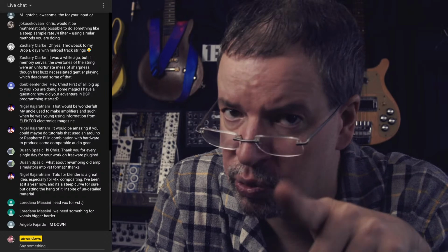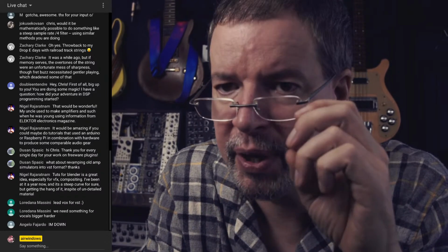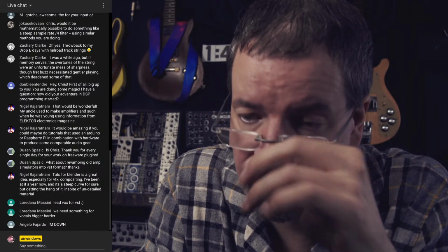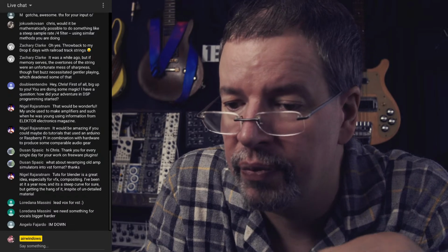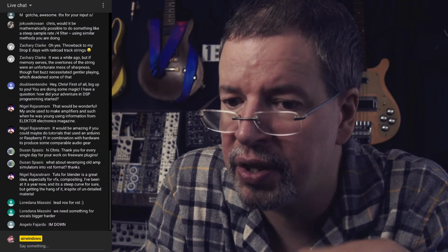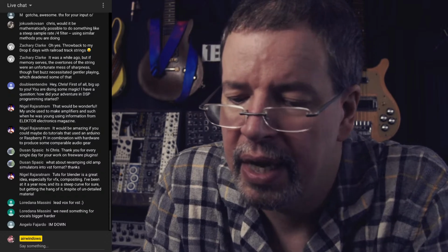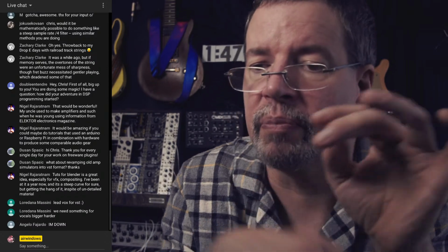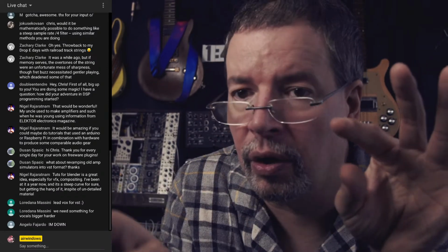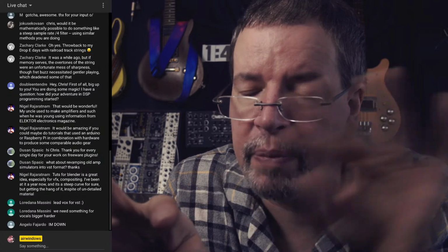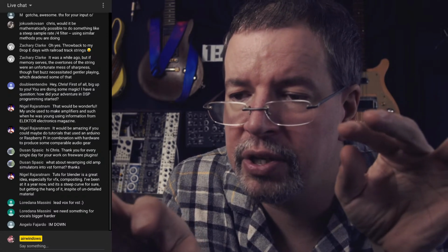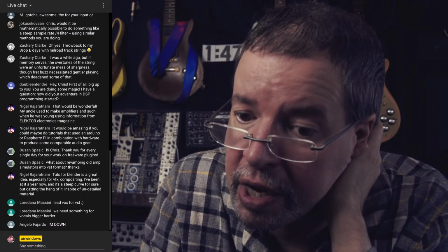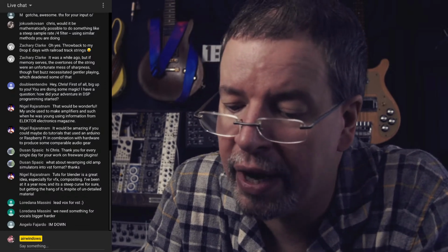You can do stuff like this in VCV Rack as well. It keeps stepping through. So you have your trigger value or whatever, your high logic value, going through step by step till it gets to the end and then getting back to the beginning again. And then the XOR gate is for monitoring a position in the middle of the long loop so that the feedback is a combination of two different points. And if you do that properly, if you set it up just right, what you get is a really good random behavior.